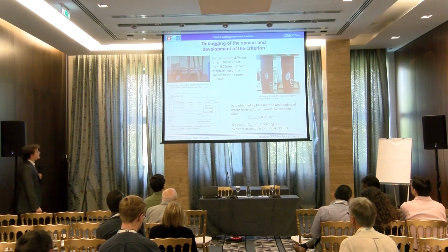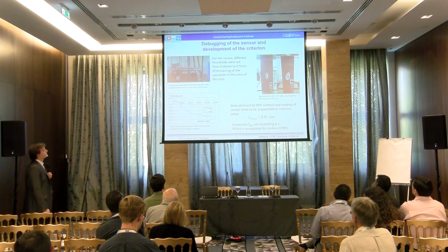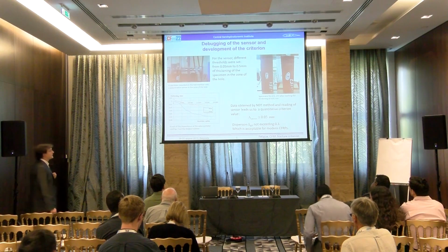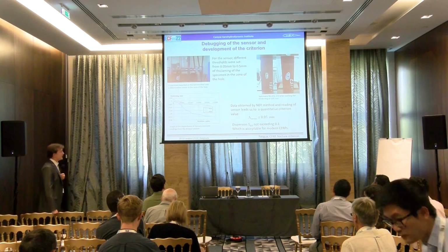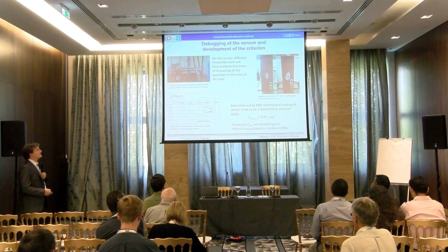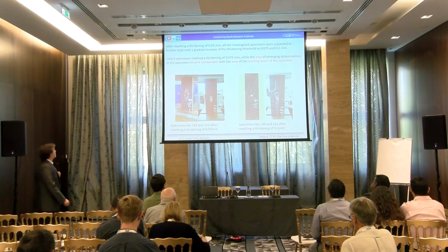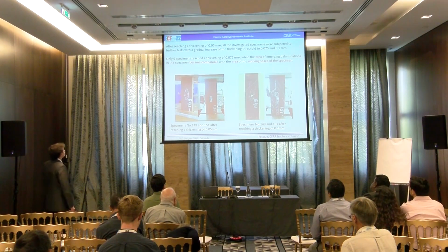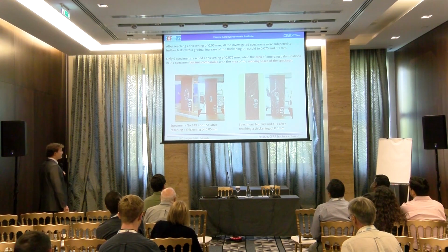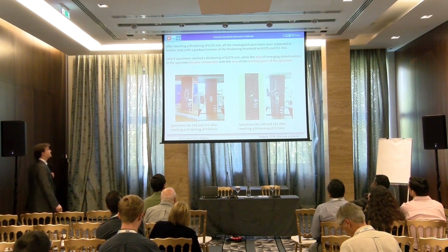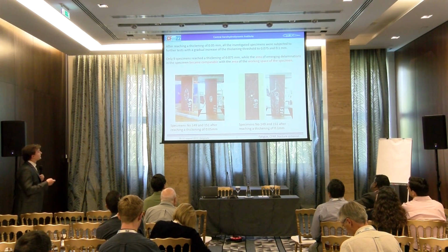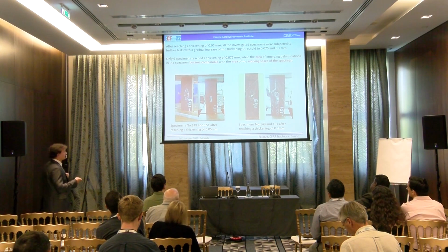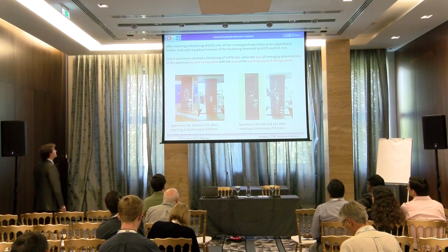In this picture you can see an illustration that after reaching the thickening of 0.05 millimeters, the areas of delaminations near the hole are similar. I should note that after reaching thickening of 0.05 millimeters, all investigated specimens were subjected to further tests with a gradual increase of the thickening threshold to 0.075 and 0.1 millimeters.